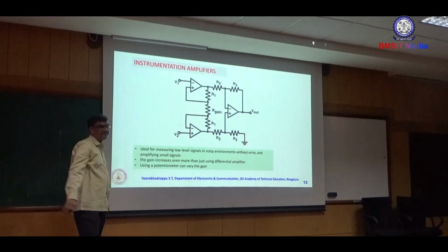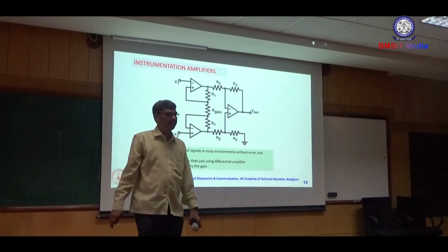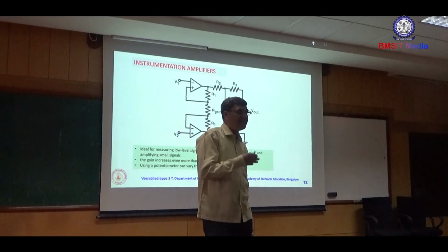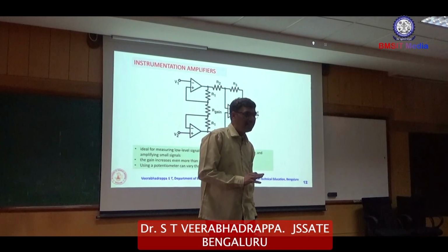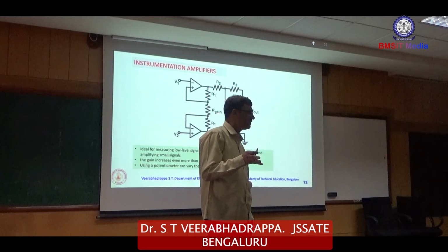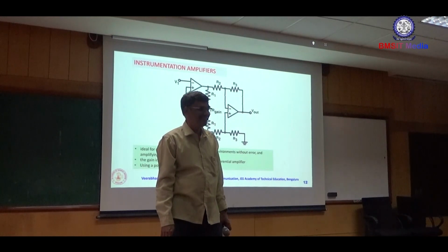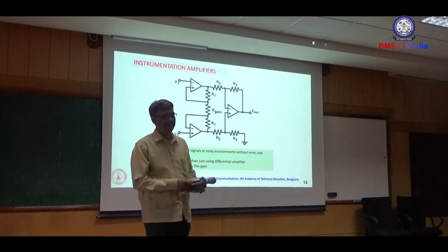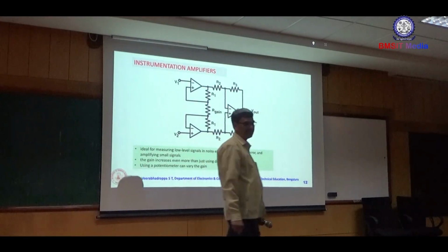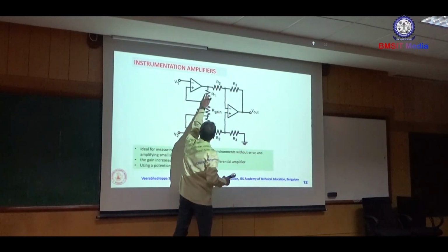How do you determine that V1 dash? We have already made an assumption that the op amp is a linear operator, that is one thing. The second thing is, it obeys the principle of superposition. So, a theorem is there again. How do you apply the superposition principle? Except for one source, you have to set all the sources equal to 0. Using that analysis, you determine the voltages V1 dash and V2 dash.